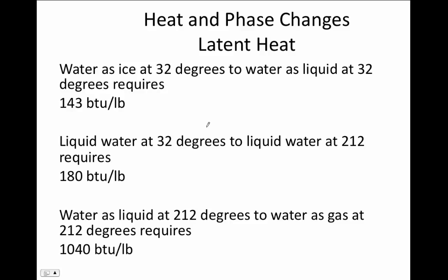And you can use this, for example, there are some waxes that melt at about 80 degrees. So you can have excess solar energy coming into a building, and you can have maybe barrels of this wax, and as the excess energy comes in, they'll melt and they'll absorb energy, and they'll actually keep the building from getting too hot.